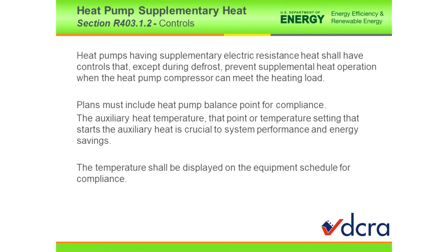So far, all the rest of the thermostats that you guys try to send in and say that automatically detect it, they don't. And I know they don't because I call the manufacturer, and we have a discussion. Sometimes even their spec sheets almost say that they do, but when you call them and talk to them, they say, nope, it doesn't automatically detect it. It's a manual input. So far as we know right now, the Nest is the only one that does that automatic detection of the balance point.